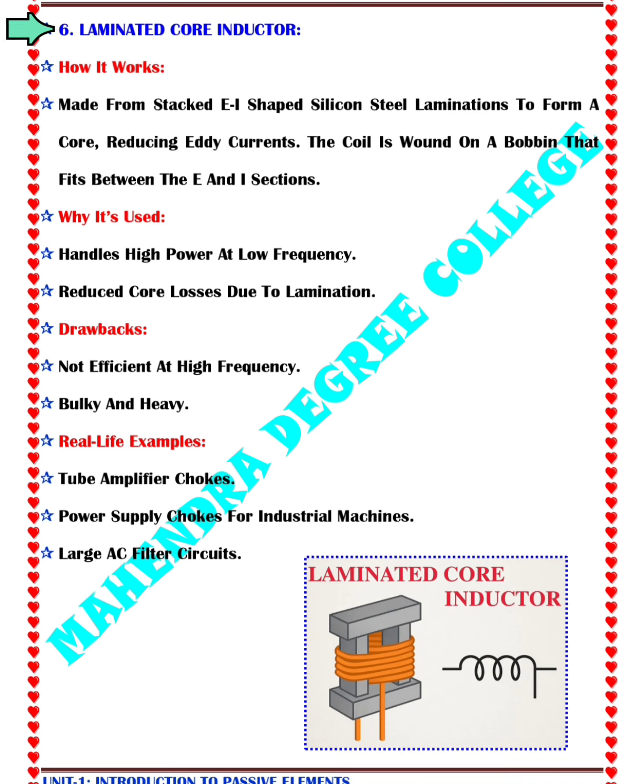We will discuss the laminated core inductor. First point, how it works. Made from stacked EI-shaped silicon steel laminations to form a core, reducing eddy currents. The coil is wound on a bobbin that fits between the E and I sections.